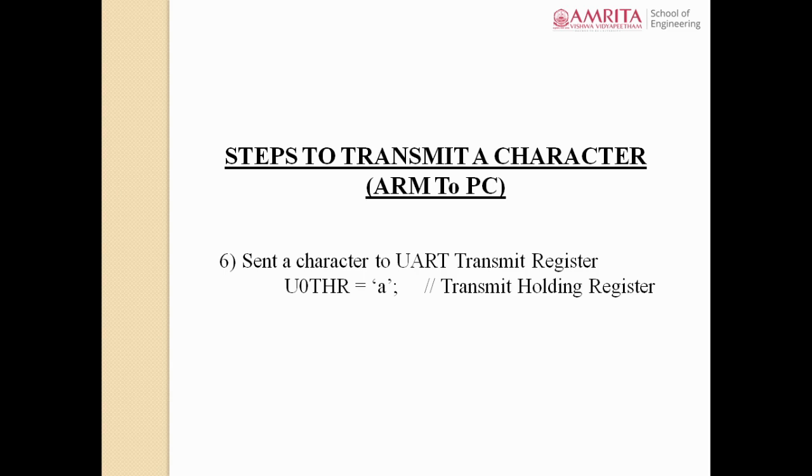Right. But one more thing you need to keep in mind, before sending the data to the UART, you should check whether UART peripheral is ready to receive that character from the user. Right. Because sometimes the UART peripheral may be busy in sending the previous character that I have sent already to UART through this register. Say for time being, you may have sent another character, say C, before sending my current character A, to the UART.